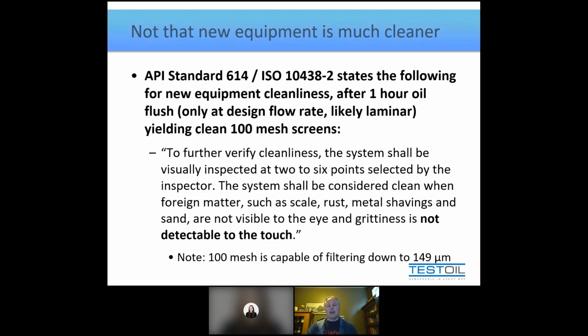Well, what that is implying is that you don't need secondary pumps. You're going to use the system's pumps to circulate the fluid. Well, system pumps typically don't flow that quickly, right? They're only meant to handle a low flow rate because they're just trying to circulate the oil fast enough to lubricate and remove the heat and whatever else they're doing.